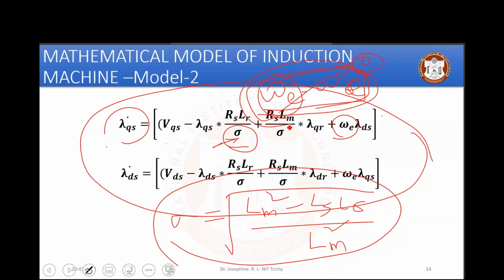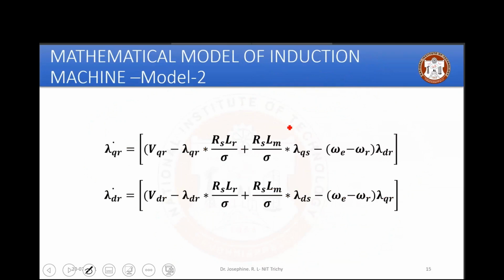Your system is going to behave in each pattern. There are different controlling methods in vector control based on your representation, like whether you are considering your model in the rotor reference frame. That does matter at the time of control. If you're using the rotor reference frame, your control mechanism will change. The reference fluxes will change. If you take the stationary reference frame, it again will be changed. So it is up to you how you choose that. It's the same thing here: it is with respect to the stator, and the same with respect to the rotor in a different model. Okay, let us simulate this first.